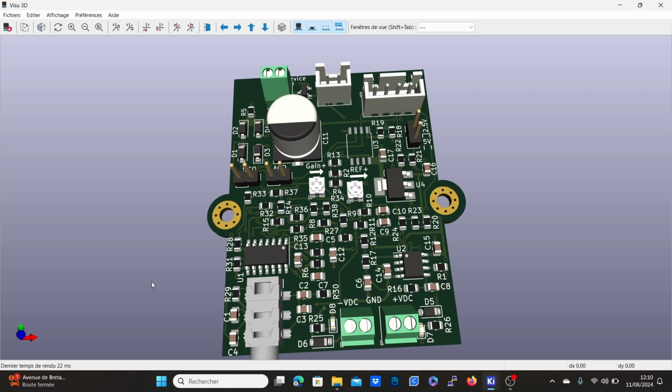And I highly recommend that you first check that the components you want for your PCB are available before even starting routing, because it can be really frustrating to start looking for the components and see that you have a shortage. Avoid using fancy values, for example 50 kilo ohm resistors.